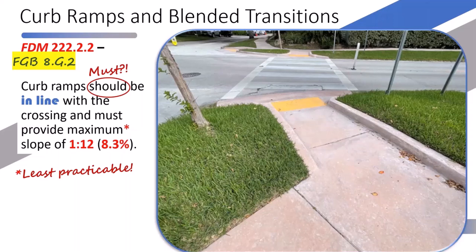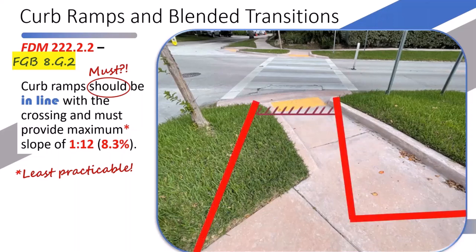I don't think so. I think that with a little bit of shifting of the curb lines, we could provide a curb line alignment that is in alignment with the crossing direction. And we can provide that clear and effective communication by providing these non-visual, physically detectable elements that can communicate the direction of the crossing to those who might need that extra information. Because the information is available to someone who does not have a sight impairment.